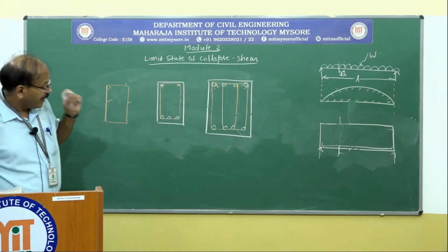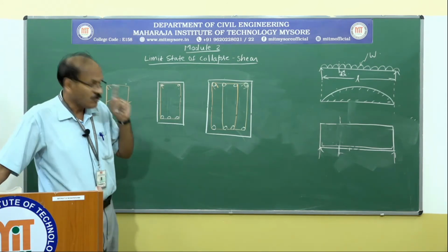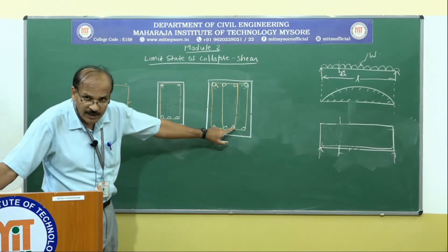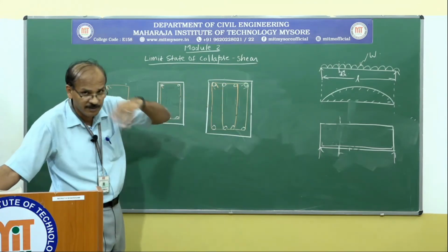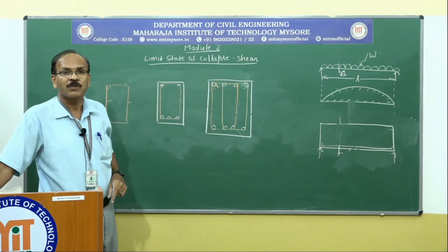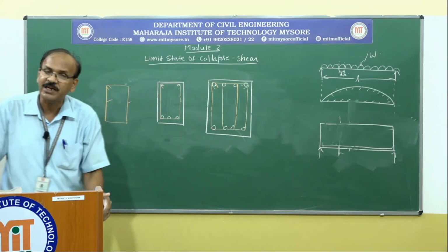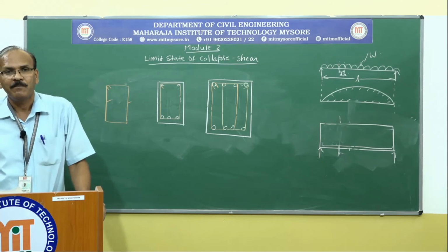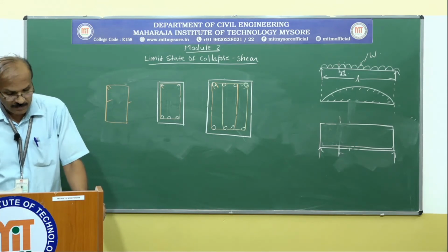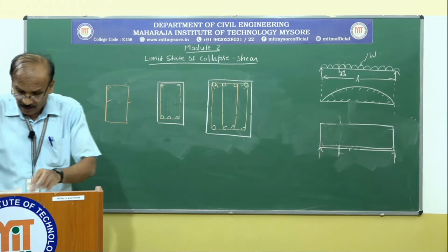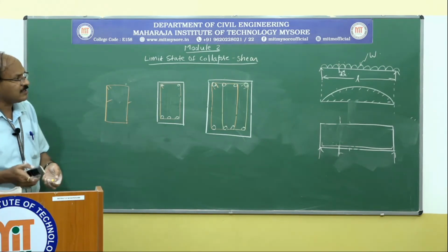So it is very important that you provide not only the tension reinforcement and compression reinforcement if required, you must provide the reinforcement to take care of shear as well. Is it clear to you? Now, what are the critical sections for shear?